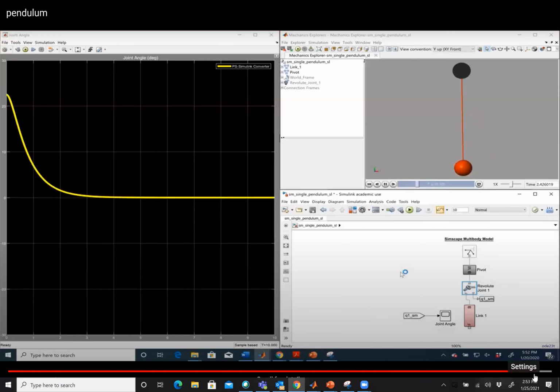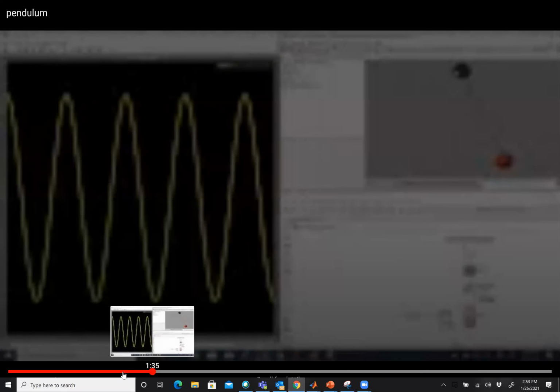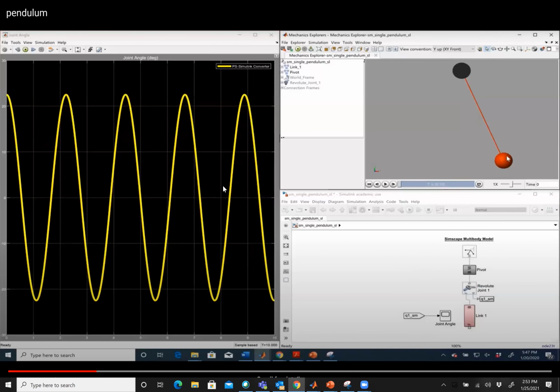So the thing about a second order system, and the reason I like to say it this way, is I can get this weird interaction between the energy storage elements. In this case with the pendulum, I start with basically all potential energy, convert it to kinetic, get it back to potential on the other side. And this oscillation is basically happening because the energy storage elements with no losses are just sloshing energy back and forth between them, okay?